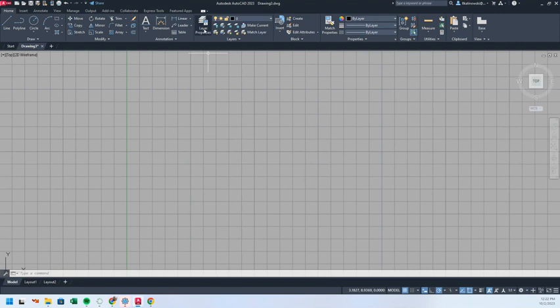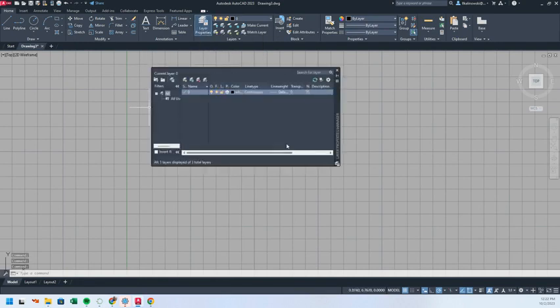We want to start creating new properties, new layers. So right in the middle of your screen where it says layer properties, go ahead and click on that. You should get this pop-up box. The very first picture has like a yellow starburst with 3 stacks of paper. Go ahead and click that. That's how we'll create a new one. And it is an object layer that we're creating.